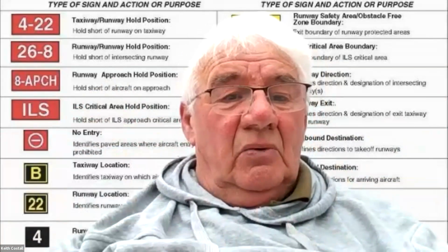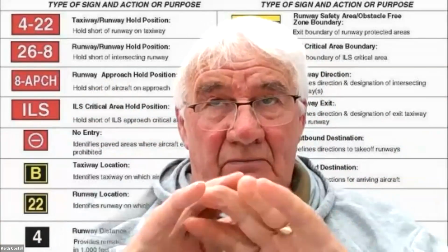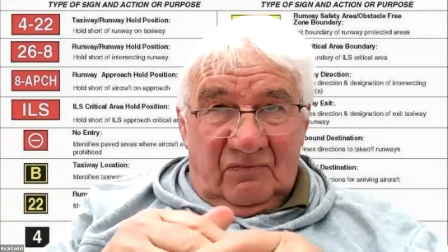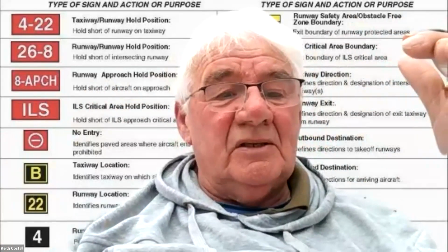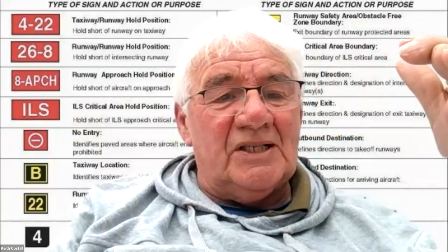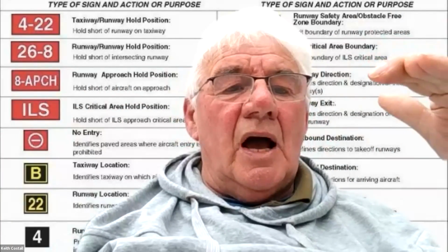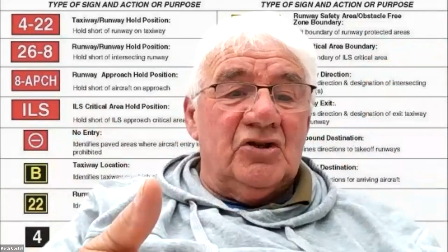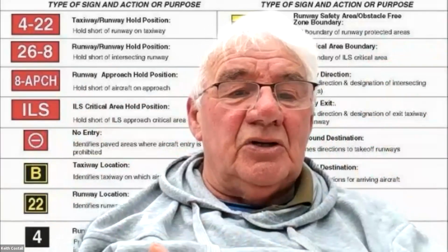Because clearly we need to achieve a desired height for the most demanding aircraft, for example, 9 meters, but we have a minimum height of 6 meters, for example, as one example. So I always demonstrate how to do a back check to see what the wheel clearance is for the various aircraft that utilize it.